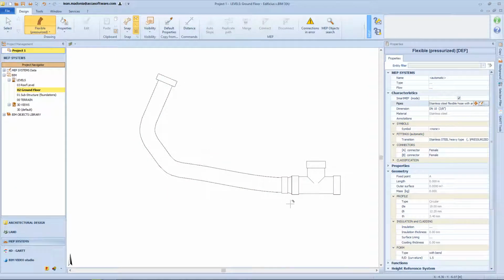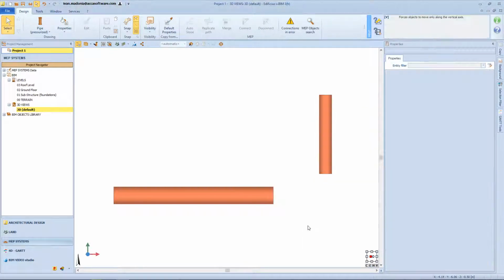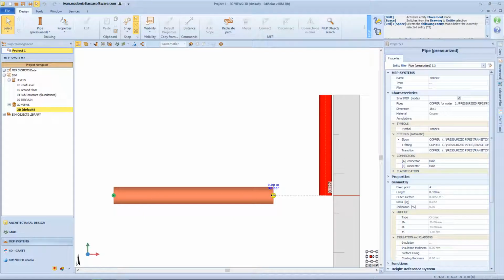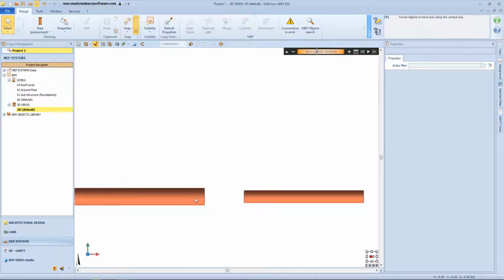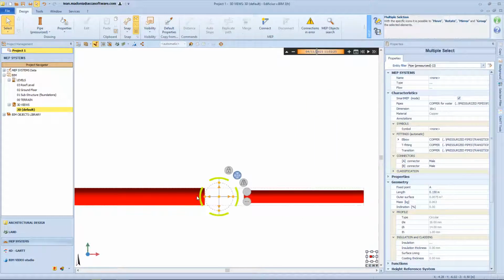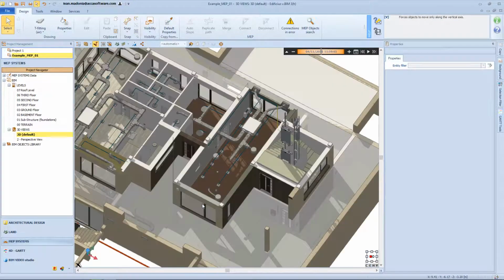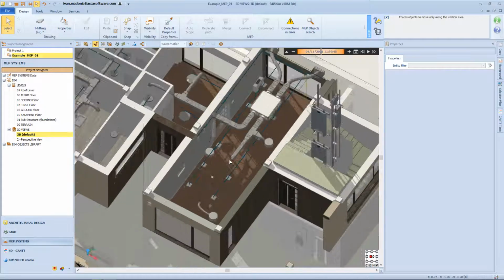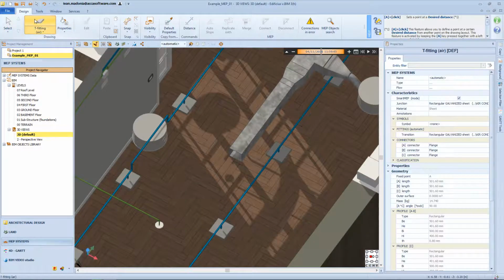If two pipes have the same shape but different dimensions, these are connected utilizing a bend. Both the bend and the transition set on the pipe are set automatically. The transitions between pipes described can be obtained after setting the right automatic fittings, also using the connect command. The automatic fittings, in addition to being generated by connecting pipes together, can also be entered manually and individually from the drawing menu, using the Smart M.E.P mode.